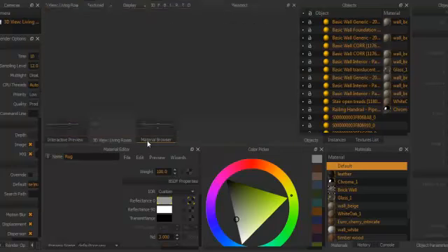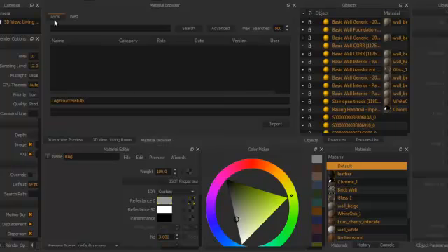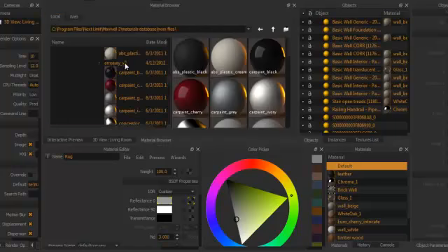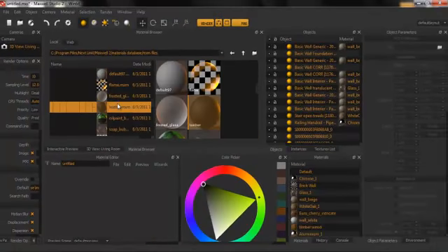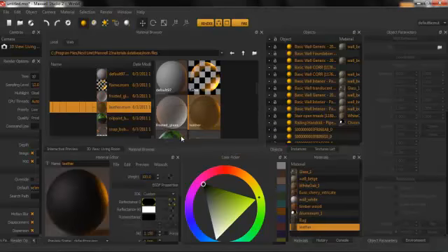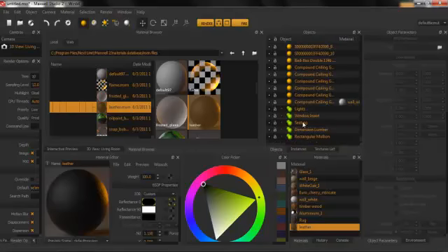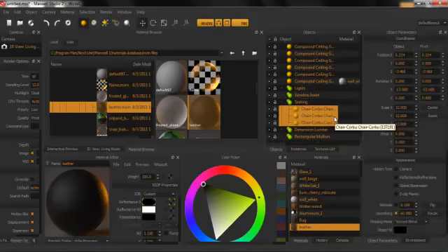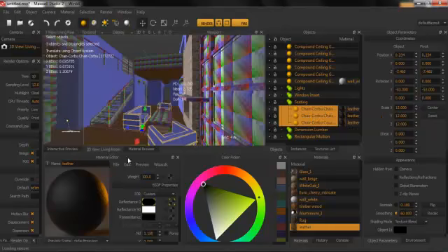First, we will look for a material in the Material Browser panel in the local library. On the materials database, we will find a leather surface. Click and drag it to the materials list to embed it in your scene. By selecting all objects in the seating group on the objects list, drag the leather material onto your objects. You will notice in the viewport that now the chairs no longer have a default texture to them.